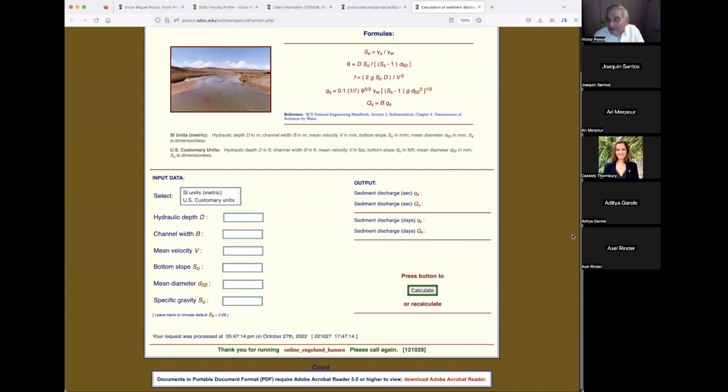The only method that I developed that I think is my own method is the one that you had already calculated, which is the modified Lane. In the case of the Lane equation, we made it a sediment transport equation because Lane had not done that. Lane had just said there's a relationship between the discharge, the slope, the sediment discharge, and the diameter. But we made it an equation, a relation. Therefore, meaning that by doing that we had developed a sediment transport formula.